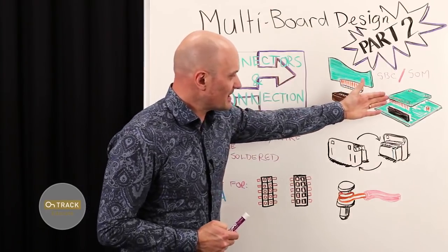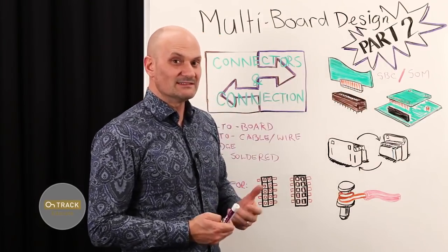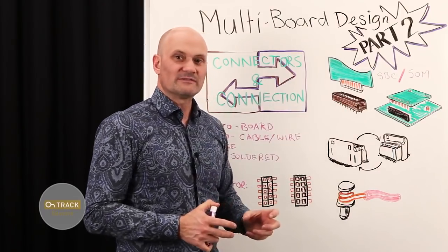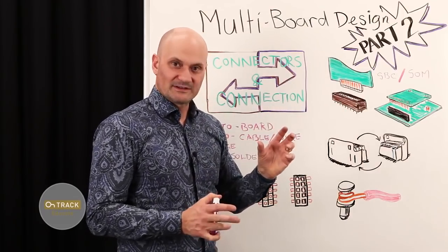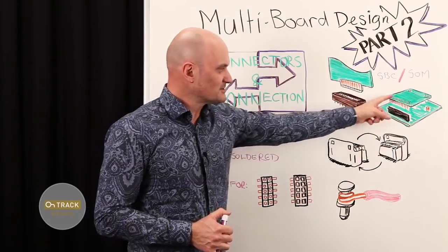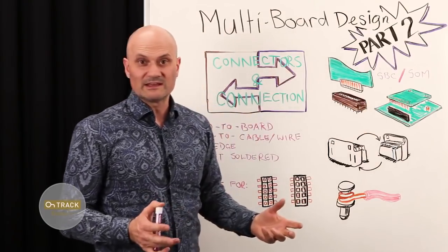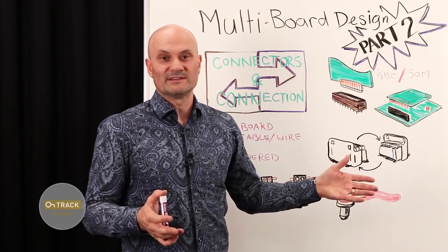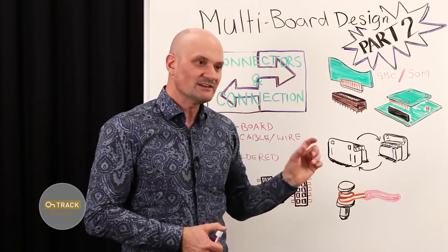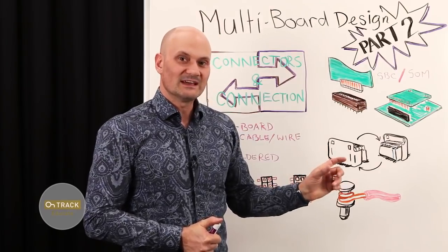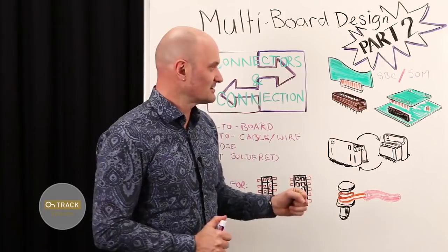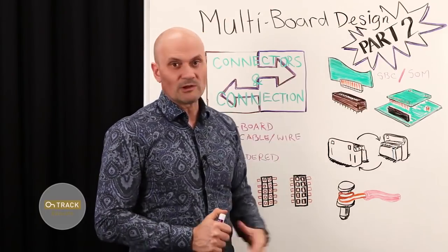And coming back to that, I mentioned the number of pins needed. So the first big trade-off is pin count. You have a physical constraint of your actual assembly, and obviously there's only such a size connector that you can put into that physical space. So can you get the number of signals you need in that space, along with appropriate ground return paths and power supply handling?